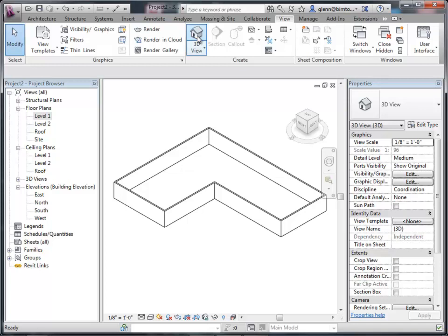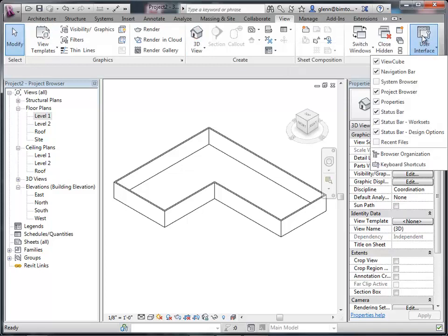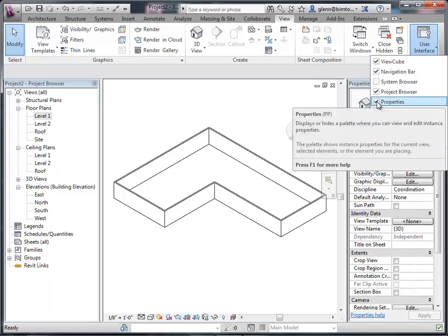It's like the properties window is hidden. No worries, that happens every once in a while. It's very easy to hide it by accident. There are a couple of different ways to get it back. One is to go to the View tab and User Interface, where you'll see the choice of whether the properties window will show. You can turn it on there.